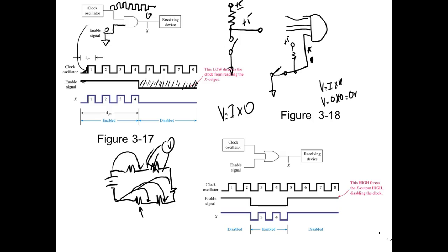But a switch is different, right? Understand. So here we're using a switch, but you got to understand, in digital, we got to use switches, right? Somewhere. So like this whole keyboard right here, this is just hundreds of switches, right? You understand? And these switches have got to give me legal highs and they got to give me legal lows. Right? Does that make sense? So somewhere there's a pull-up resistor inside this keyboard. So when I close the switch, I get a 0. When I open the switch, I get a 1. Right? Does that make sense? Sort of. It's a little different the way the keyboard works.